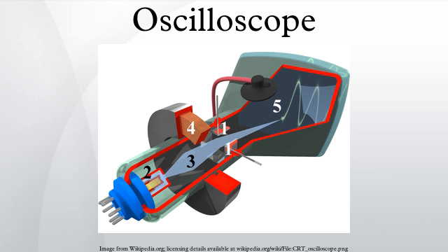In general, chop mode is better for slower sweeps. It is possible for the internal chopping rate to be a multiple of the sweep repetition rate, creating blanks in the traces, but in practice this is rarely a problem. The gaps in one trace are overwritten by traces of the following sweep. A few oscilloscopes had a modulated chopping rate to avoid this occasional problem. Alternate mode, however, is better for faster sweeps.